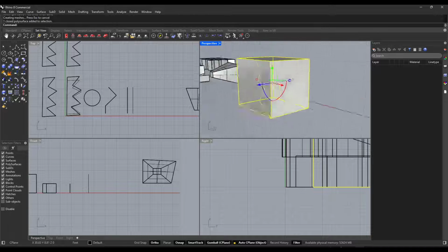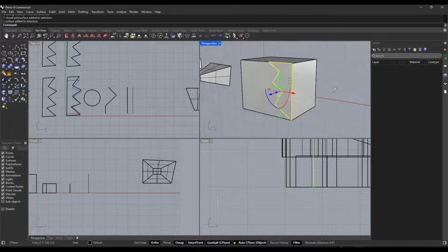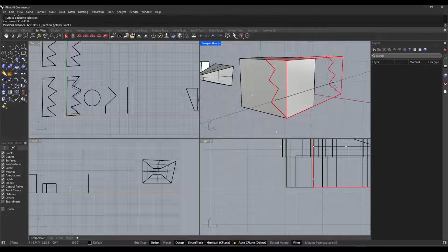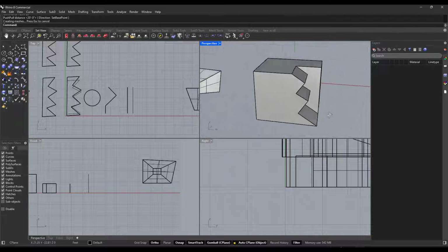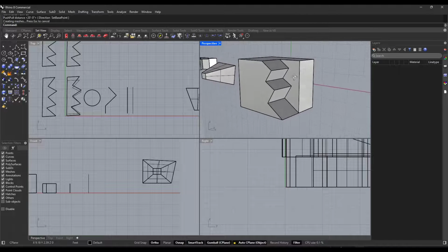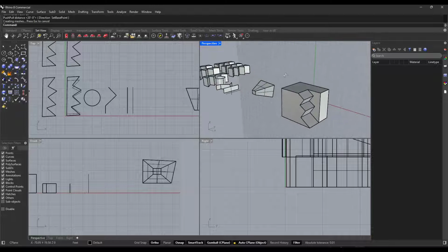But again, notice what I've done is I've split that face. So if I do a Control-Shift and mouse over this, I've drawn across this surface. Well, now if I type in push-pull and use this tool and say I wanted to snap this to the midpoint, it's going to push-pull this back to the midpoint right here. So you can use this in order to create and extrude shapes in 3D.